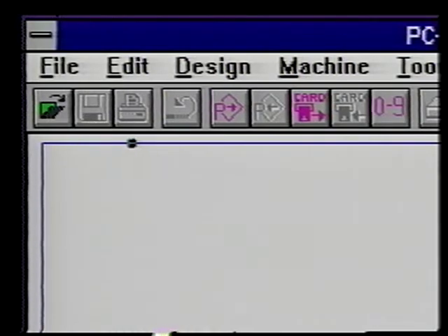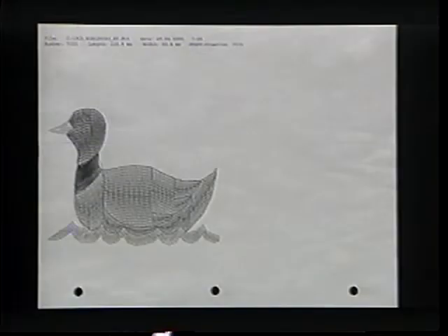This button is a picture of a printer. If you have a printer for your Microsoft Windows program, this will print a hard copy of the stitch pattern in the work area. The printing is always in landscape to enable the printing of long patterns like 9mm sequences. If the displayed pattern is narrower than the paper, it will print approximately the same size as the screen. If larger than the width of the paper, it will be reduced to fit. If longer than the paper, it will print on as many pages as are needed.